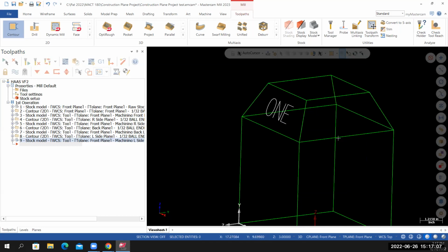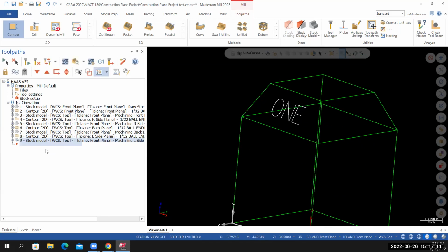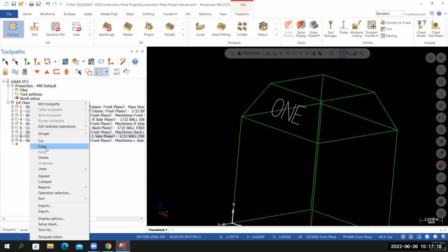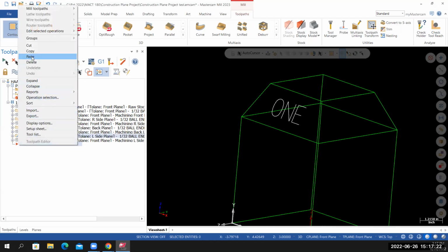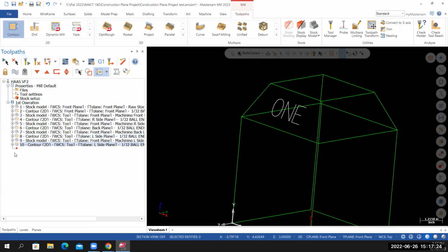We're now going to engrave the first angled face. I'm going to grab one of the existing toolpaths. Just one of them selected, right-click copy. Next to the insertion arrow, right-click paste. I need to expand the toolpath. I'll start by going into the parameters.